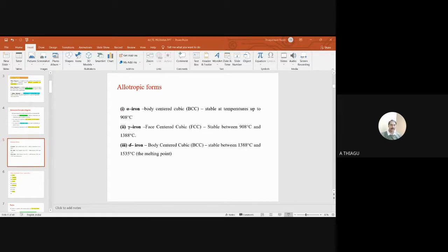The sample should be heated to 925 degrees centigrade and held for sufficient time, meaning 3 hours I'm going to hold at 925 degrees centigrade. What will happen is that the entire structure is going to become austenite, and on cooling change into pearlite. I will show the picture. So this is the information we are going to find.